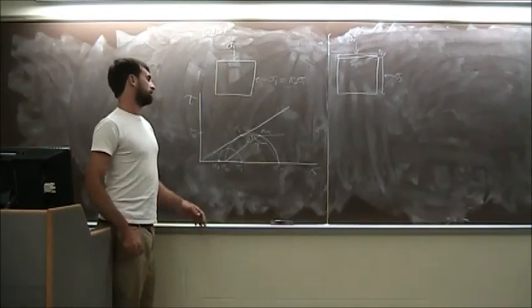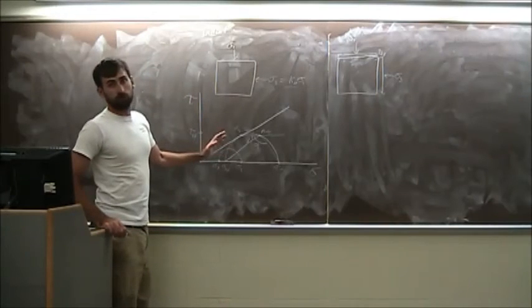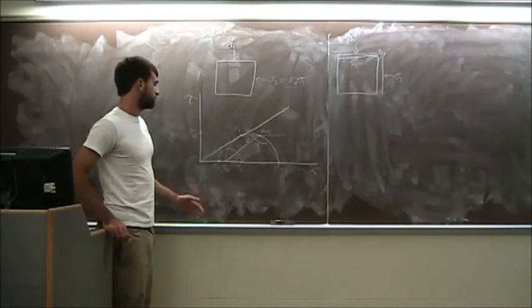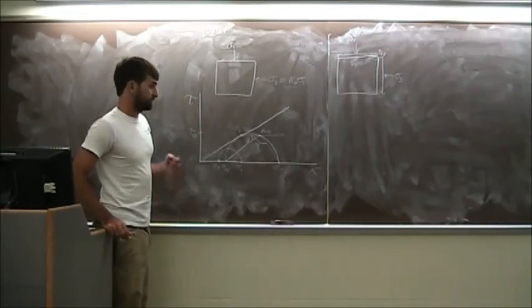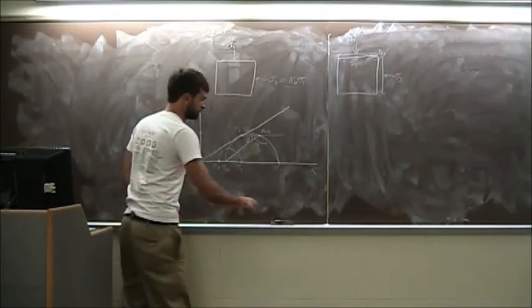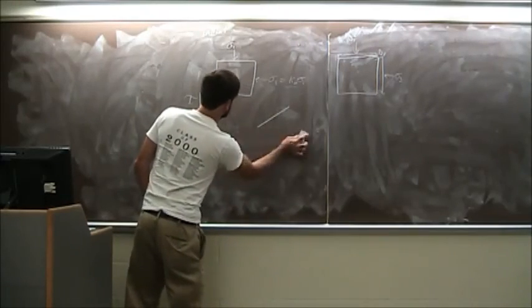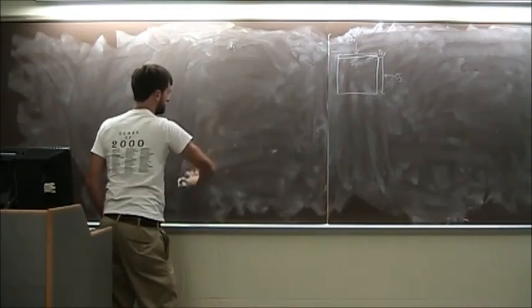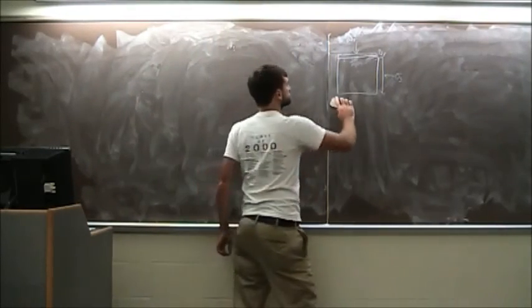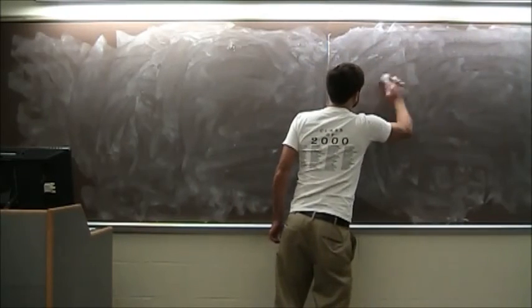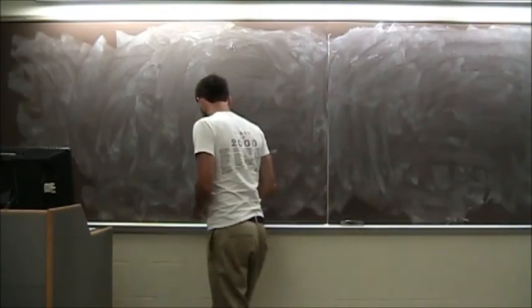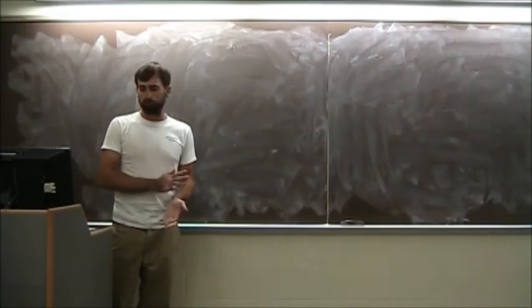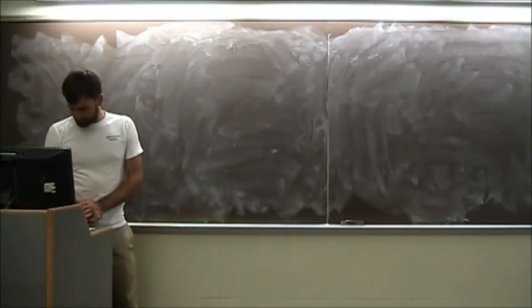So as you can see, throughout the test, the principal planes go through some rotation, which is not really indicative of the field conditions that we're seeing. So that's one major disadvantage of this test. But a couple of advantages are that it's a really quick test, it's pretty cheap, and it's a very simple test. It gives fairly good results and good estimations of the shear strength parameters. Those are some good advantages of it.